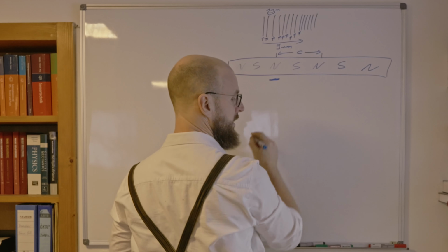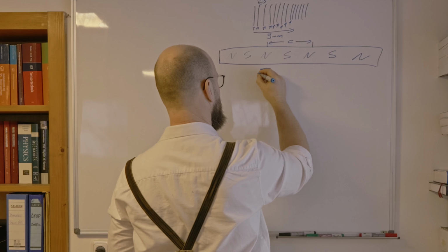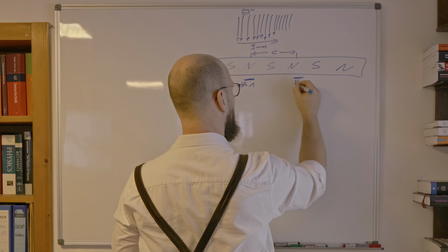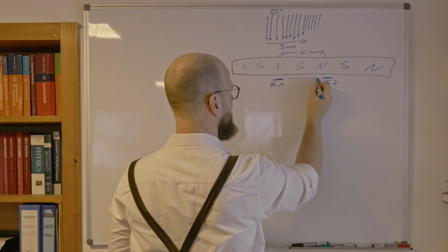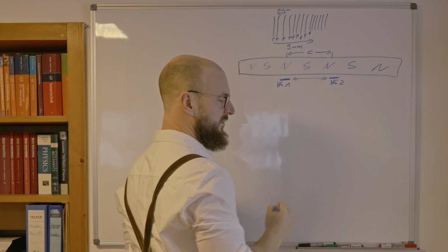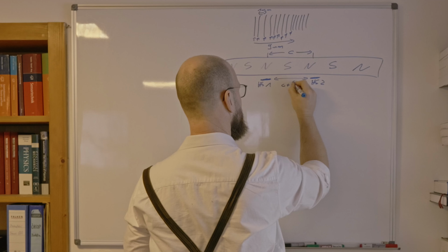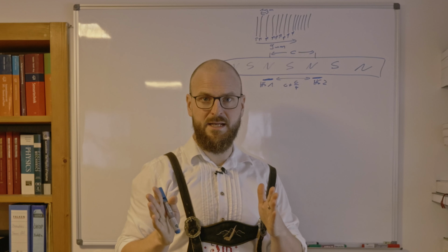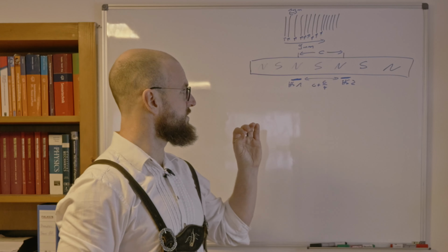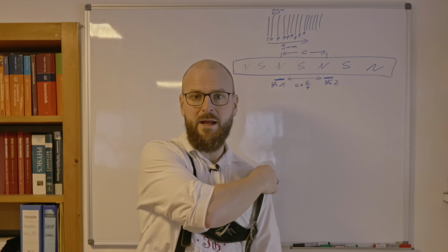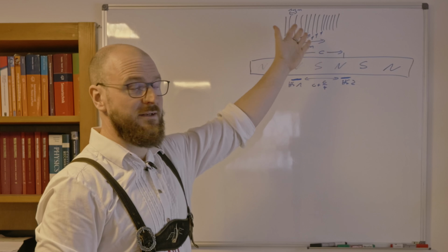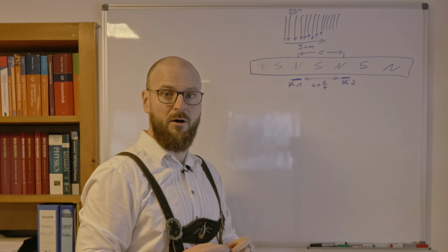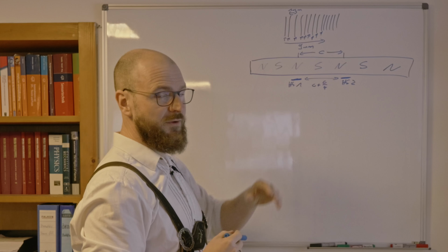We already know a Hall sensor 1 and a Hall sensor 2. And now we want to place them at a distance of C plus C over 4 of the period. So not exactly in a period C, and not using only one sensor. Why not using only one sensor? The same holds for optical measurement technology also, when using optical sensors for counting the lines.